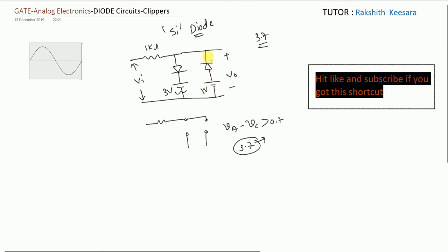if you see here, guys, the voltage across silicon will be in this direction. So it is opposing 1. So what is the reference voltage here? 1 minus 0.7. That is 0.3 volt. What is the reference voltage here? This is the voltage across silicon diode. We should draw this voltage in the direction reverse to the current direction. So here 3.7 is the reference voltage. Here 0.3 is the reference voltage.